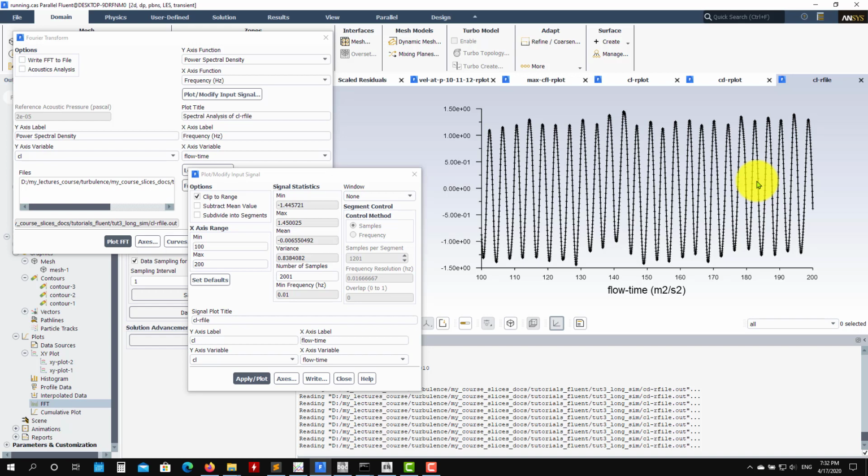We're using this case that probably is not a normal case. Now as you're doing airfoils, you won't have this strong shedding, this strong dependence, but as you're working with cylinders where you have this shedding, it's a good idea to sample in a lot of places just to get that shedding frequency. It still leaves open the problem of why the frequency of one signal is double the other one, so you should answer that. And let's do a little bit more post-processing here.